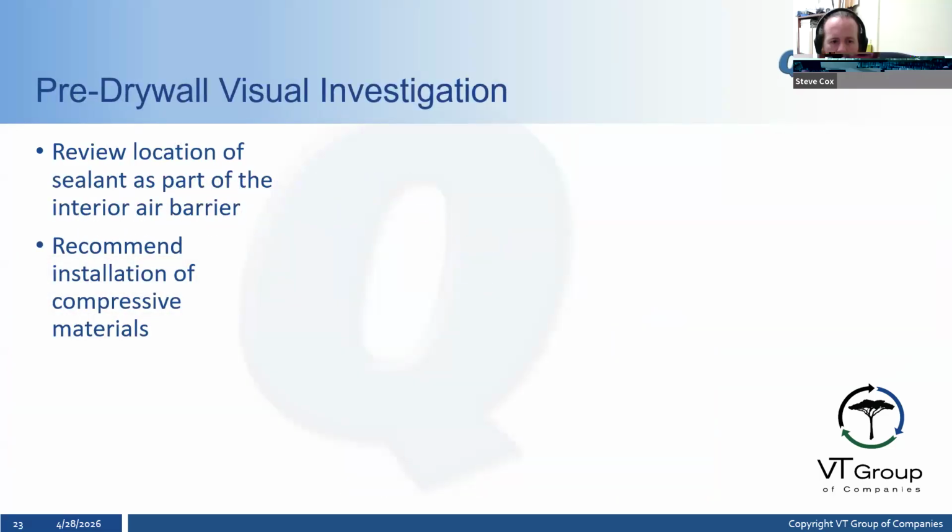So I mentioned earlier, something else that we do is a visual review. This is something that we do before we walk a site, while we're walking a site, before we blow it up, do an airtightness test. That's my language, blow it up. We do a visual review to make sure everything's going to work, right? All the windows are in, the doors are closed, the poly's all there. There's not a part that's missing. All that's going to impact the results of the blower door test and how effective it is.